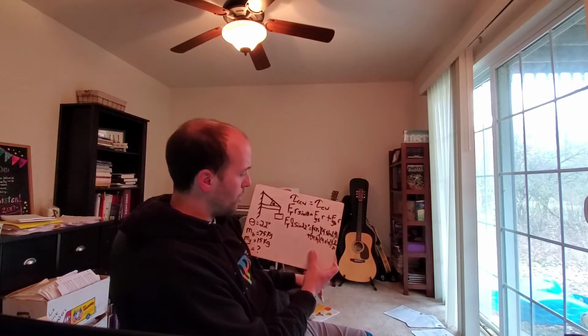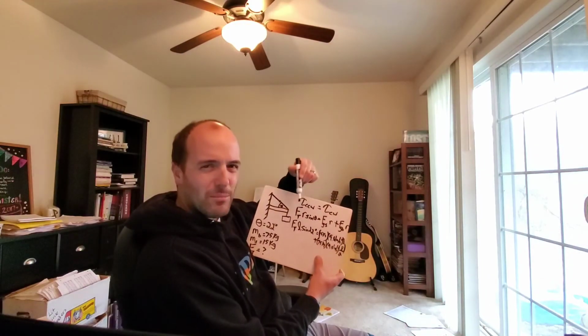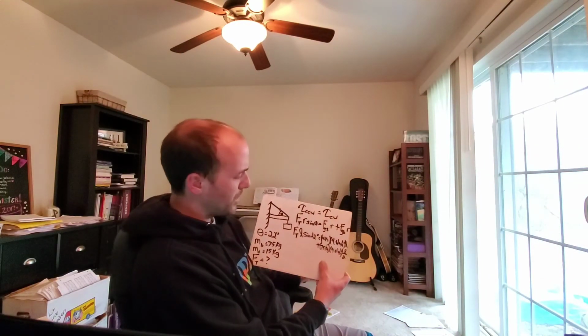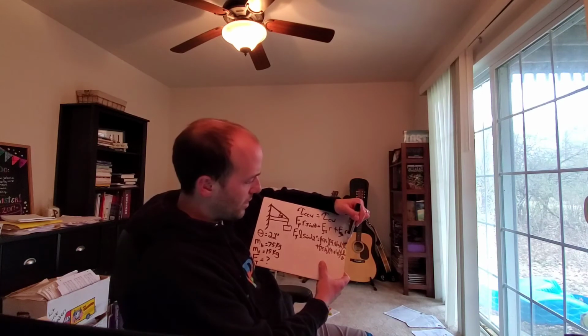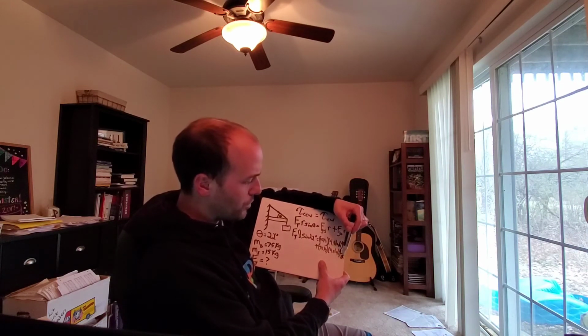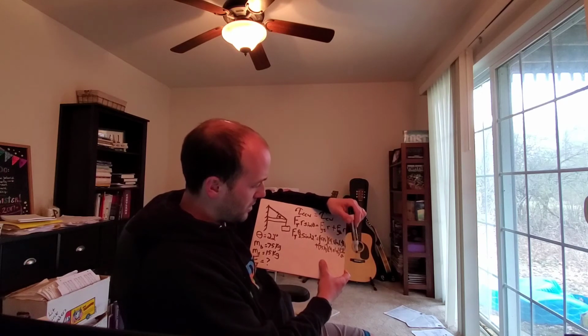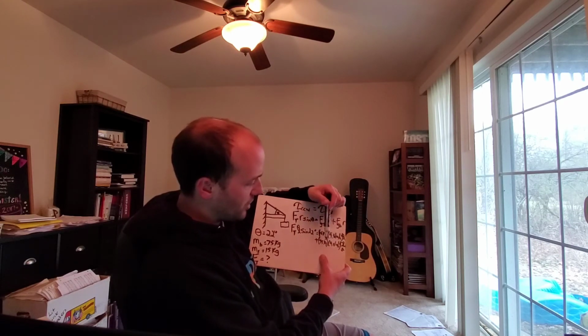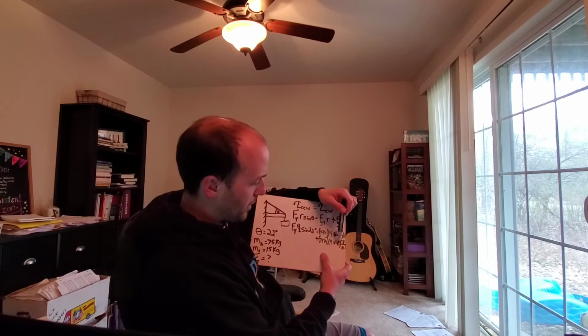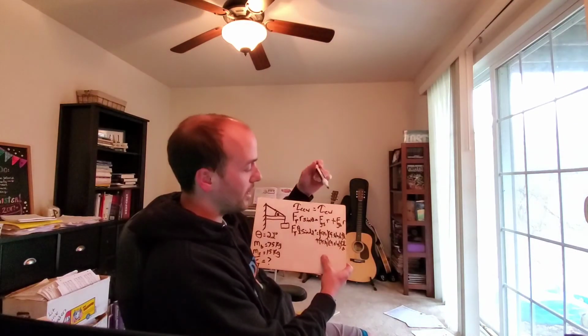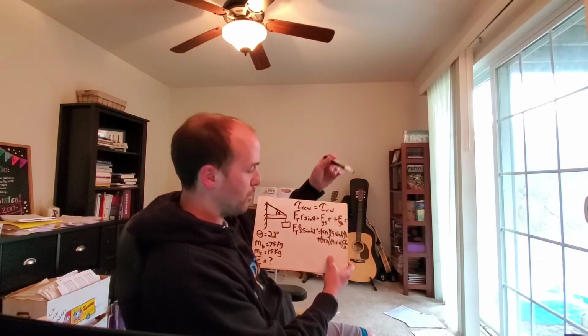Remember how we didn't have that moment arm, the length of the beam? Well, we have an L here, we have an L here, and we have an L over 2 here, so I can cancel out an L in each spot. That ends up just being 75 kilograms times 9.81, all divided by 2, because multiplying by 1 over 2 is just multiplying by half.